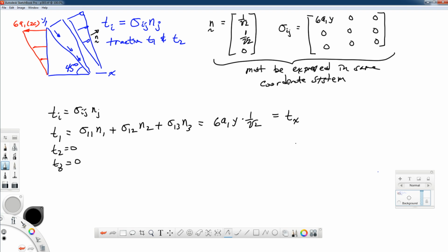All right, now this t in the x direction, that's the traction in the x direction. Remember that goes this way, at every point up this incline. What we'd really like to have instead would be some tractions in the direction normal and parallel to the inclined plane.